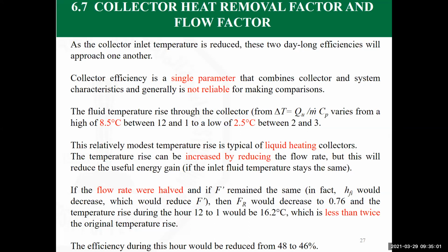And that's why in many of the air conditioning systems used for buildings, most of the buildings here have an air conditioning system with a vapor compression unit, where the Freon or the refrigerant is used to cool down water outside the building. Then water is carried in pipes into the building. For every floor, there is a room called the air handling unit, which is a heat exchanger.